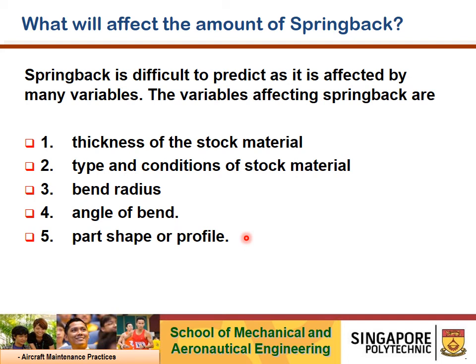You may have a very accurate calculation and mark out accurately, but your judgment of sightline placement and bending will affect the overall completion of the bracket or the channel you want to form. So all this takes a bit of work experience and more practice to make it perfect.